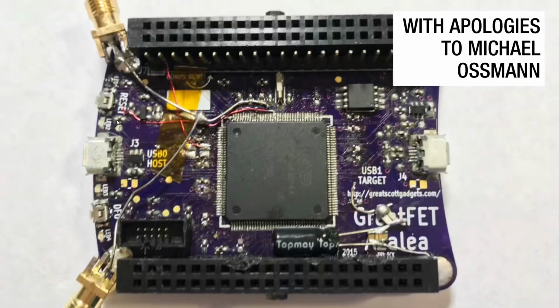I've added a couple of pretty nasty bodge wires here. One connects the VCC rail to a couple of SMA connectors, so that you can do things like inject voltage in, or inject glitching signals in, pull the voltage down to 0. Because we still want some decoupling, I have a decoupling network here that is replacing all the decoupling capacitors on the board, connected via a small impedance so that we can pull the device really readily to 0, but it can recharge the VCC bus from these capacitors via that small, in this case approximately 10 ohm, resistor.